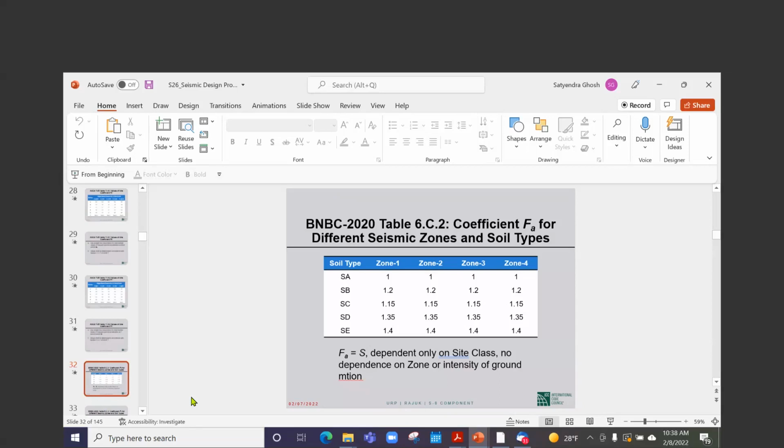If you want to look at all the historic earthquakes and exclude the entire range where the past earthquakes have been strong, then you won't have much to work with. So my advice would be, don't worry about it. Design your building properly according to code, and then if there is resonance, that is fine. The building will still do okay.